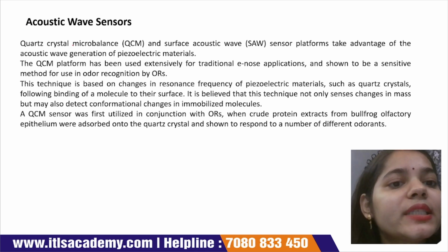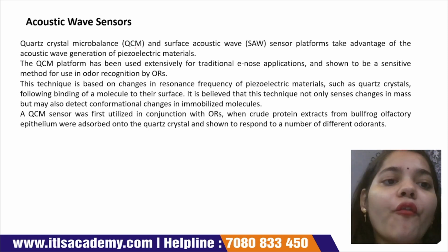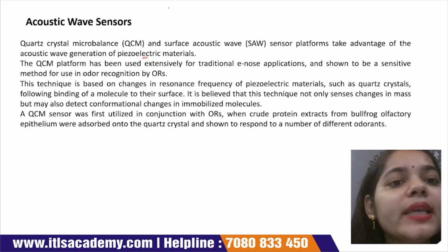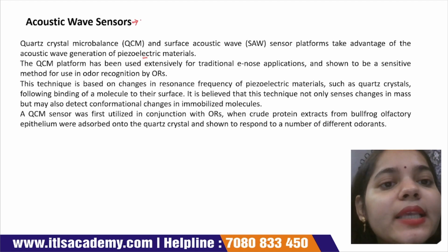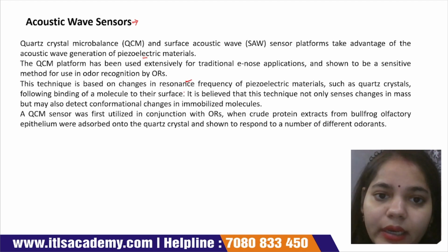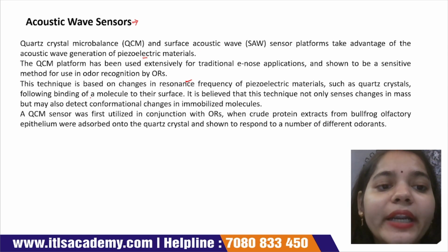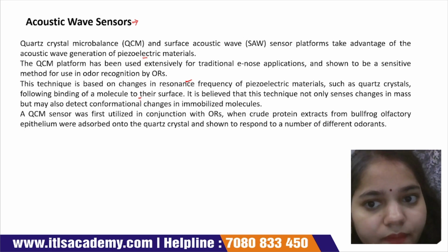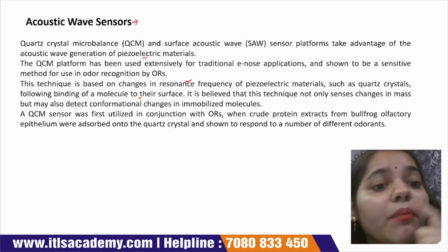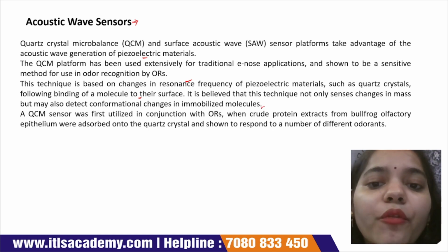Quartz crystal microbalance and surface acoustic wave sensor platforms take advantage of acoustic wave generation by piezoelectric material. Basically the function of this sensor is based on changes in the resonance frequency of the piezoelectric material, which may be a quartz plate, following binding of molecules to the surface. It is believed that this technology not only senses changes in mass but also detects conformational changes of the immobilized molecule.